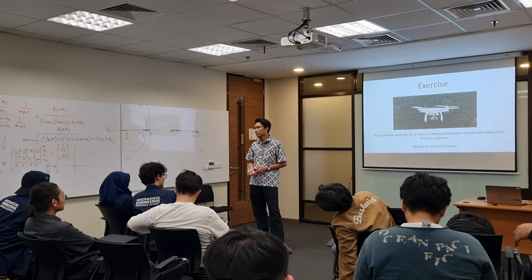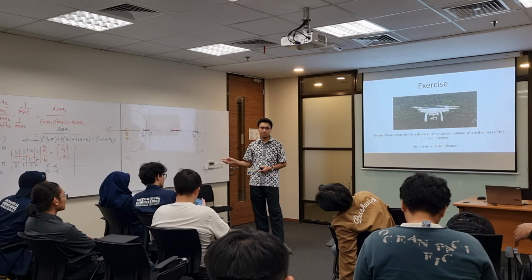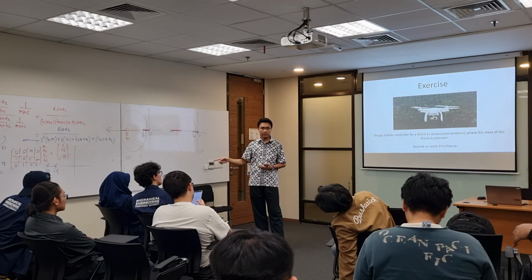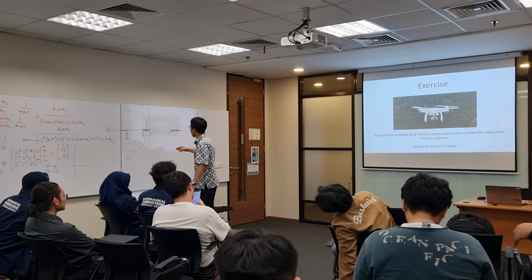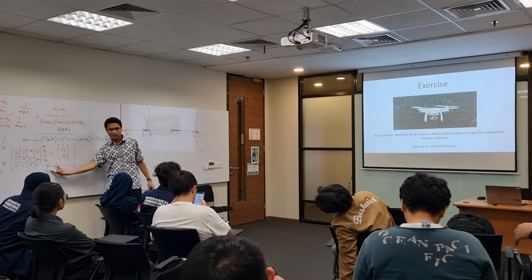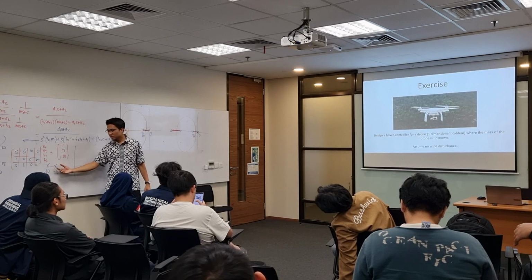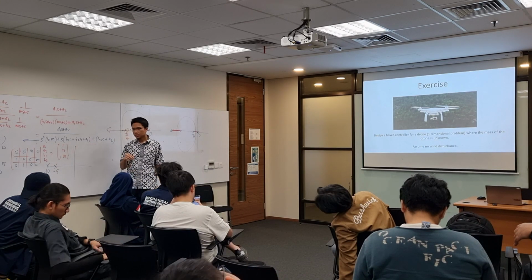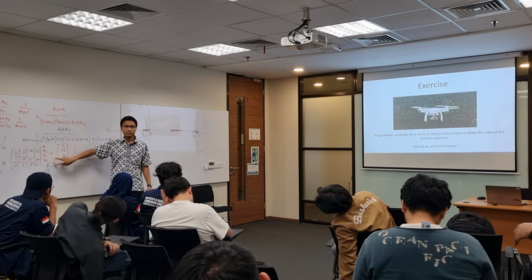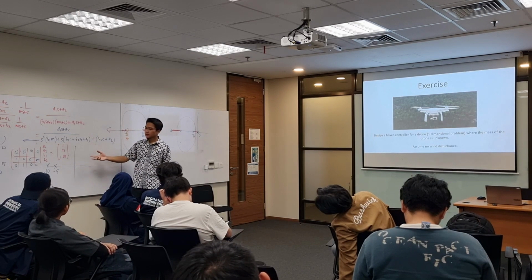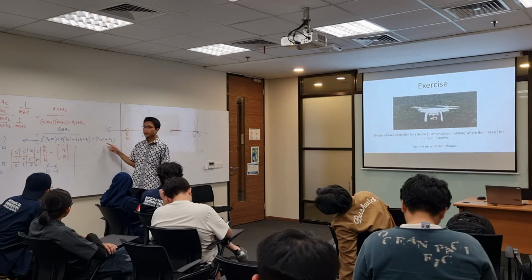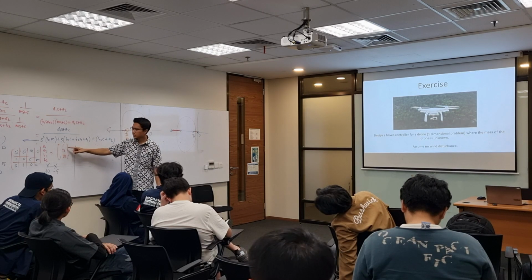And then after that, you design your pole location, because the response of your system is defined by the pole location, right? If let's say you want your system to be overdamped, then your poles have to be distinct. If you want your system to respond fast but small overshoot is okay, then you might place it at a complex number. So that will affect how you choose this B1, B2, A1, and A2. Okay, it will change these numbers, right?